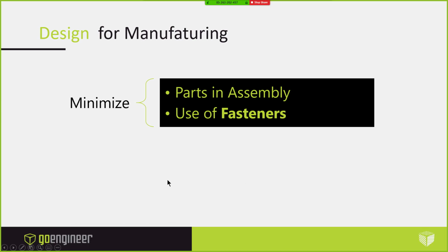So again, just to reiterate the impact of minimizing parts, this is less parts to design, less parts to document and revise. It reduces our bill of material, the parts that we have to receive in, inspect, store, and handle. Also, there is less labor or energy to get those parts created, as you saw with the sheet metal part and the rod. We cut some cost down by not having to have so many parts made at a sheet metal house.